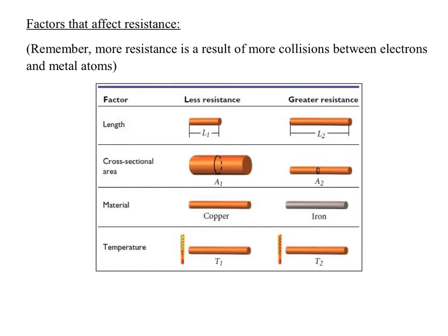So in this case, we're looking at the same idea here. As the wire gets narrower, those electrons or charge carriers are much more likely to interact with the metallic atoms and thus slow down. Okay, so again, we have a wider cross-sectional area with less resistance. So what kind of a relationship exists there? Indirect. Good. Indirectly related. As area decreases, resistance increases.